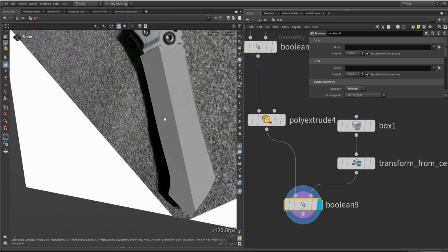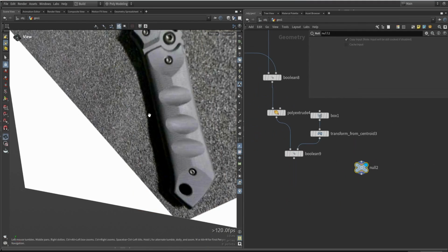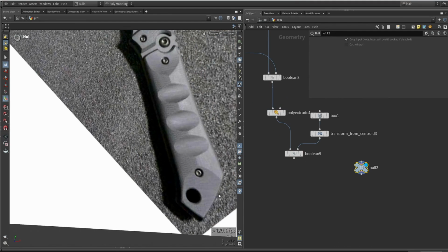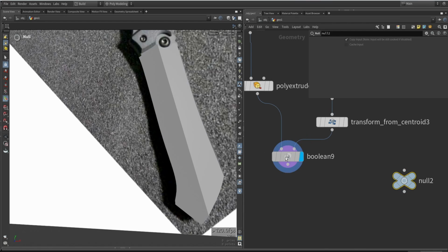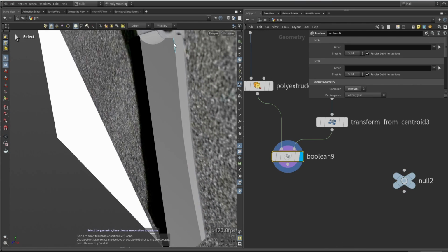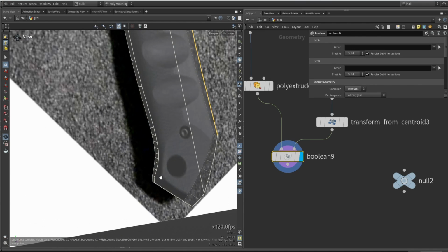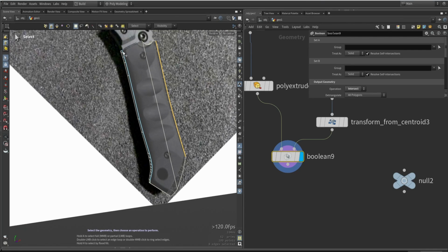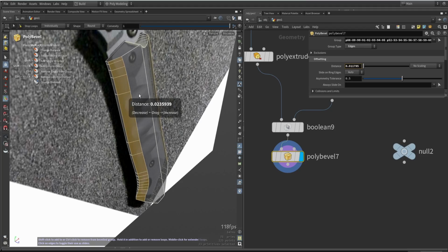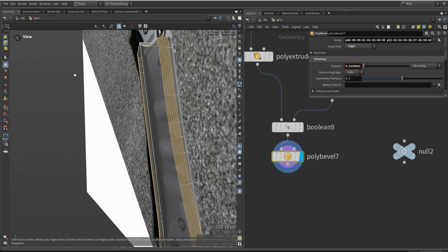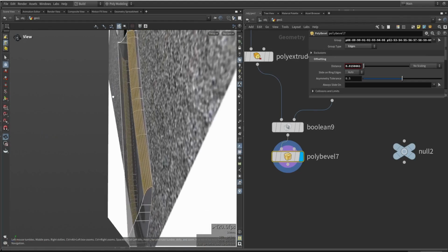And then let's also bevel this shape, because we can see from the reference, so I just hide it here, we can see from the reference that the sides of this handle are beveled a lot. And I can actually do this right now, or actually could have done this before. So let's see if I press now 2 on my keyboard and select here the side edges. Let's do the same here as well. Let's select the edges and then hold C and then bevel mode. And then we can roughly get some beveling in like so. So we're already making that big bevel here on the side.